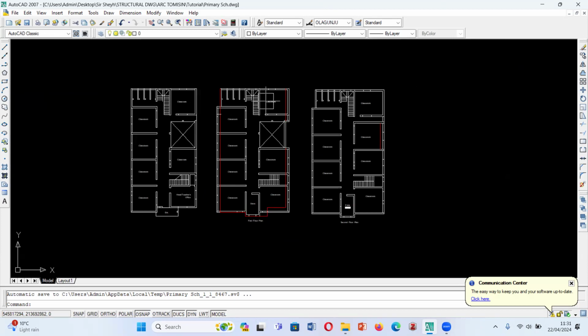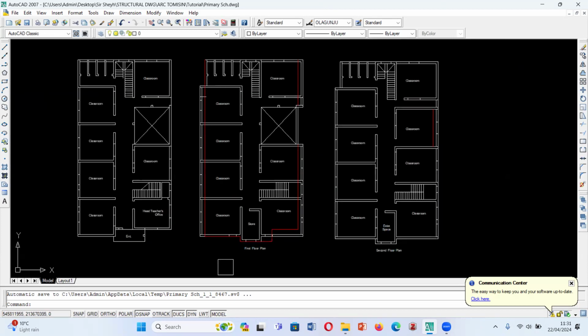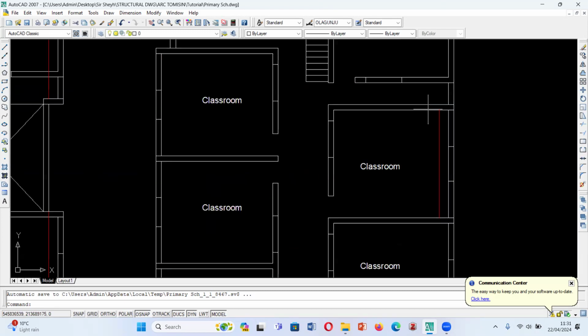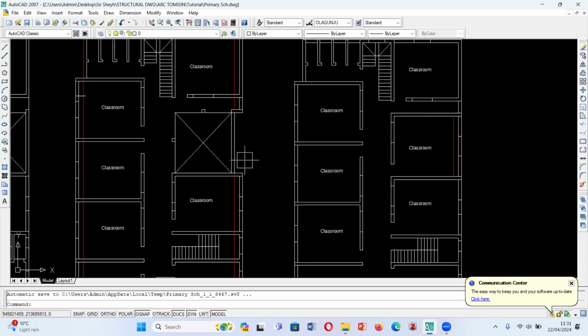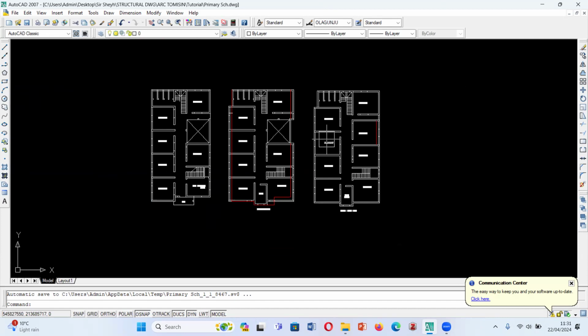So the architect has made it very easy for me to know where the cantilevers are. Then you would agree with me that this void here is just from here to where we have this red line, then all the way here, just like this. There is nothing here from the ground floor to the first floor, but it is covered on the second floor. Okay, so those are some of the similarities you want to look at, because those are the things that instruct how to grid and how to panel your building.